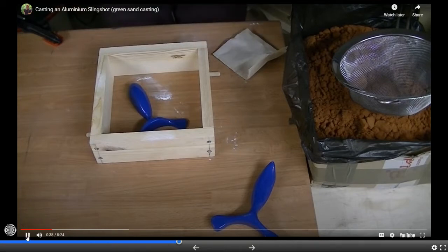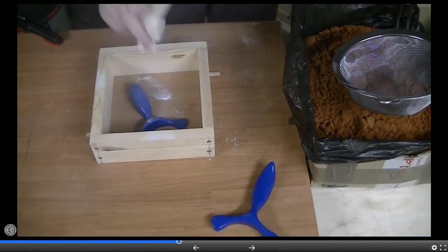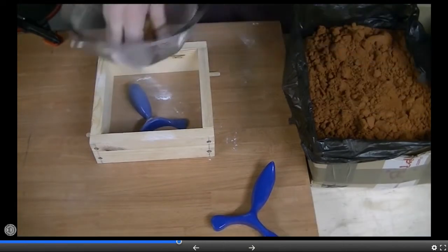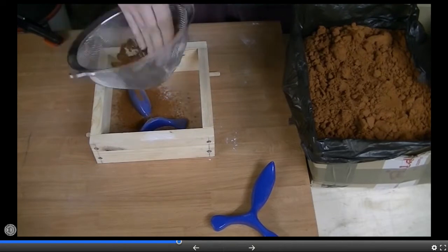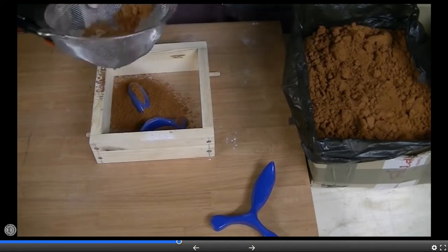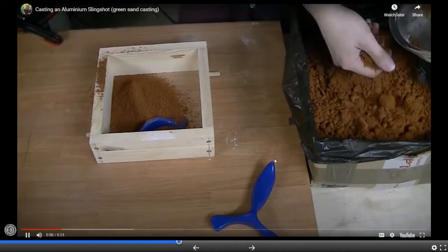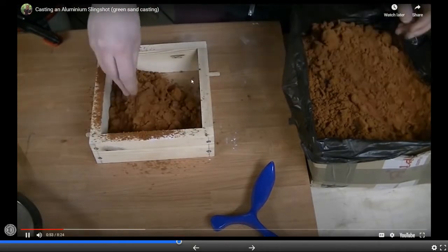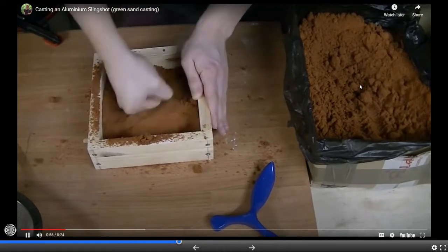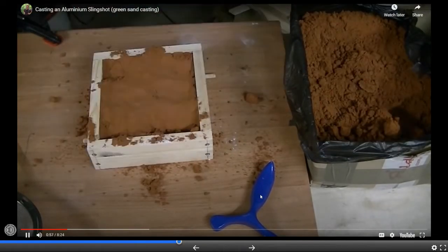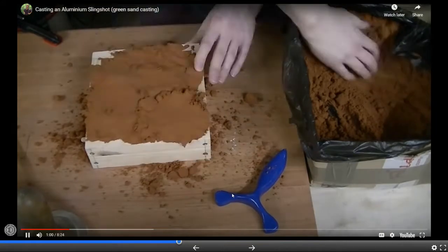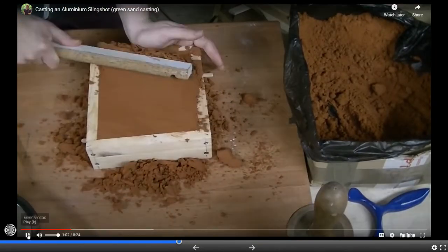The flask is completely packed with sand. The talcum powder is to help to remove the pattern from the mold. You can also see at first when he puts the sand in, he filters the sand because you want the finest sand particles to be closest to your pattern. And then after you have an initial layer of sand around your pattern, you can just pack whatever type of sand in there. It doesn't matter because that sand is just supporting sand.